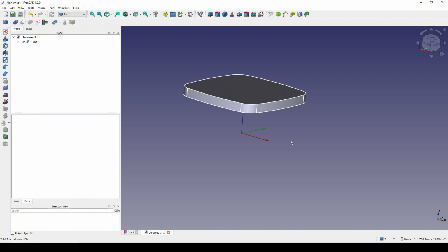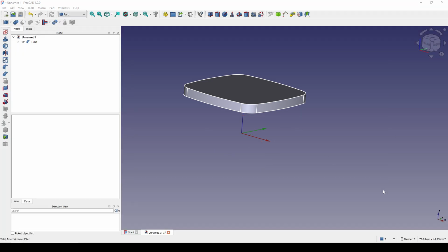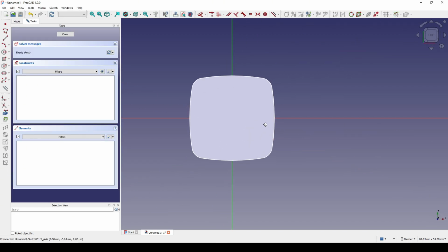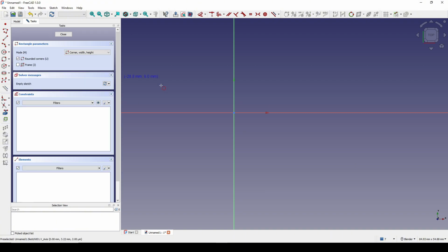Next, I want to create another base sketch on the top view, also a round rectangle. From there, I will create multiple plane curves to connect in between and fill in the surface in between. I create another sketch on the top view and view the section. Creating a round rectangle.